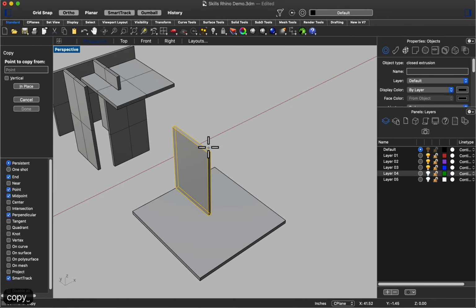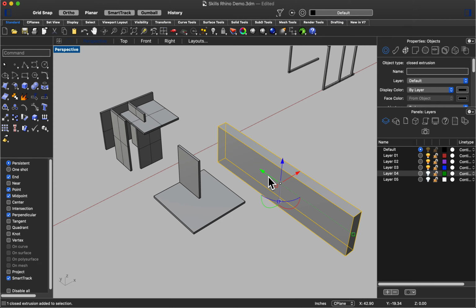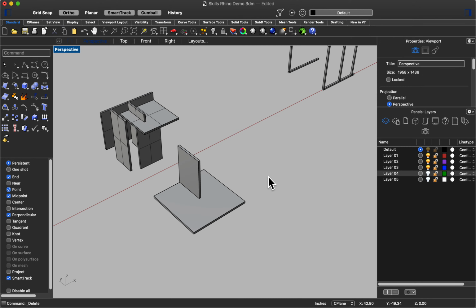If you scale this in 2 dimensions by just typing scale 2D, you'll see that it's asking for a similar thing, but what it does is it will scale the thickness to match the length. And in this case, all of my planes were the same thickness, so I don't want that thing to be scaling that way. So scale 1D is definitely a good thing.